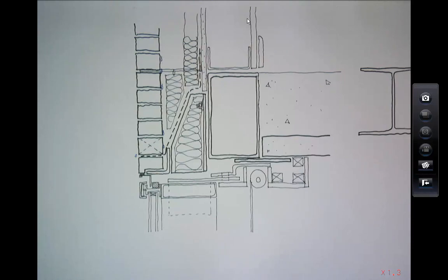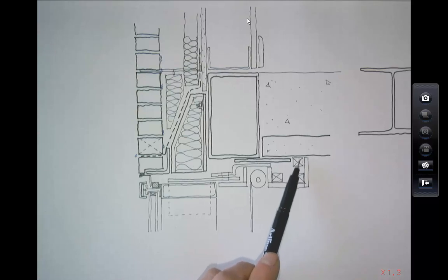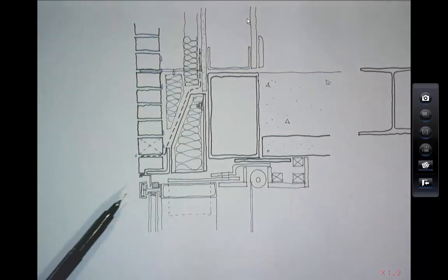Okay. How do they fix the MDF on the ceiling? The MDF? They fix timber battens. So if they're fixing into steelwork, they use a shot-fired fixing, a little explosive. So you walk on site and you hear a bang, and you're not sure what's going on, but they've never let me use one. And if they're fixing into concrete, they sometimes just drill it and use a plug or a bolt. Yeah. It's not a really stupid question.